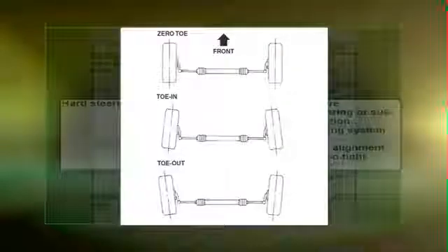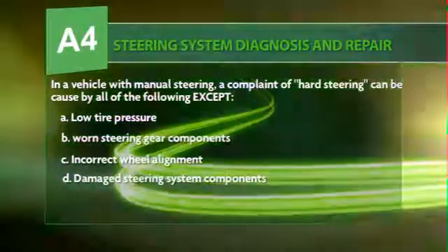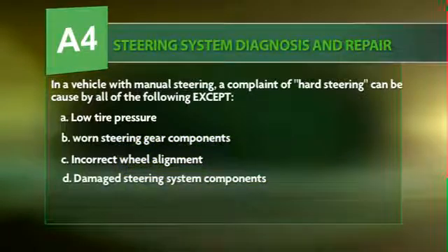And if the steering gear itself is just too light, causing hard steering. So we go back to that question and we see one of those answers that's wrong. That's the only one to select because we're looking for the "except" in bold here. Low tire pressure we talked about, that can cause hard steering. Worn steering gear components, I didn't see that on the little symptom chart. So let's talk about worn steering gear components.